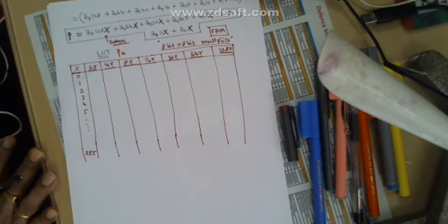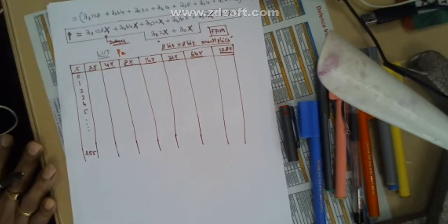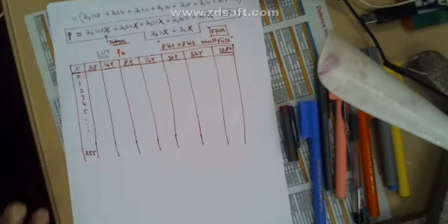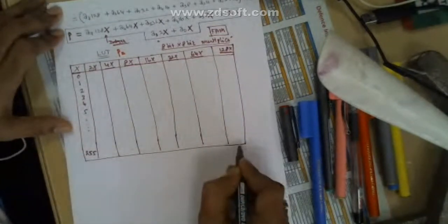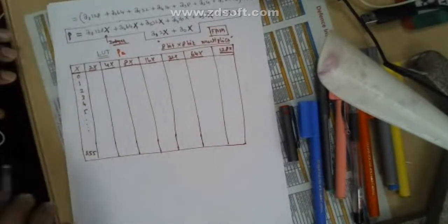When you multiply 128 bit by 128 bit, your result will be a maximum of 2 times 128 bits, correct? That long a register and that long a multiplication is possible in the FPGA. So we need not worry about the array declaration or using the array design in the FPGA. Here it is restricted to 255 because right now we are interested only in 8-bit multiplication.